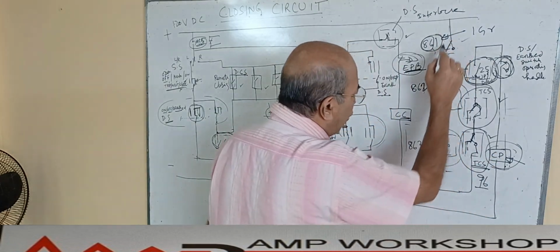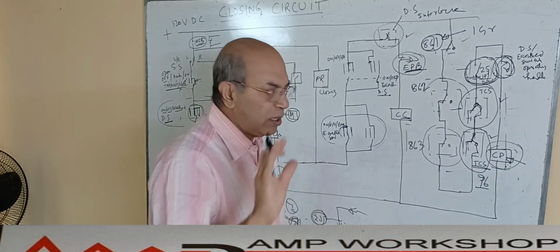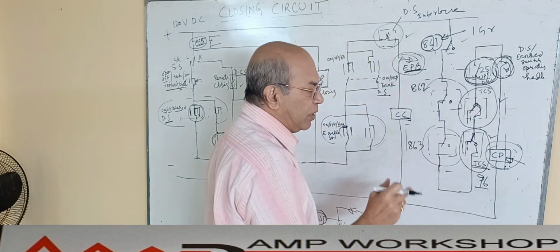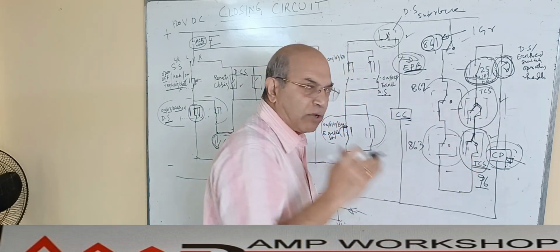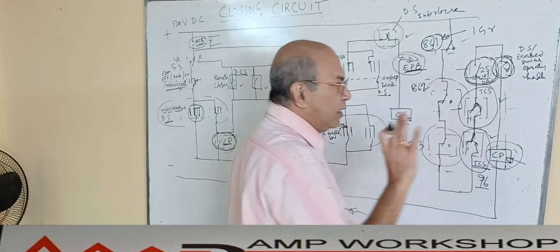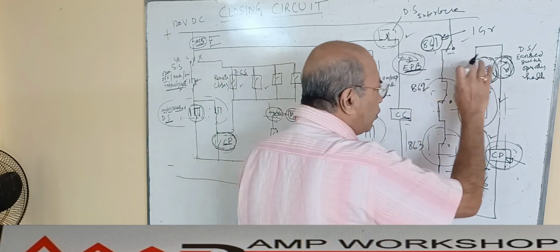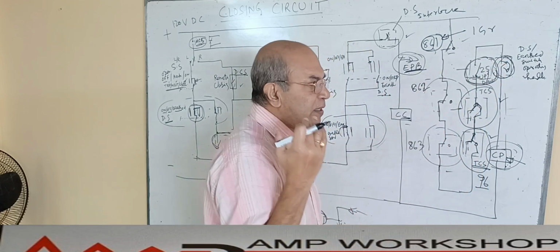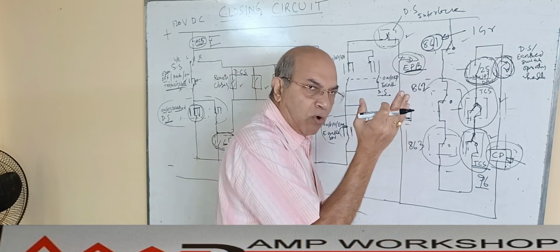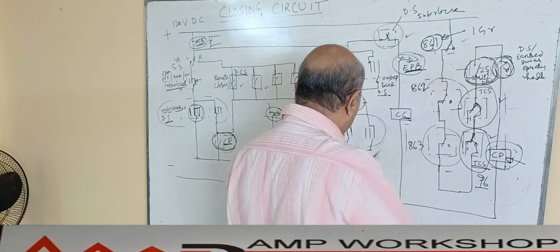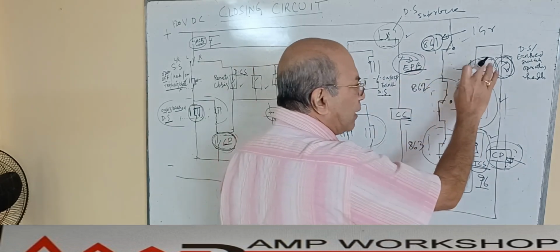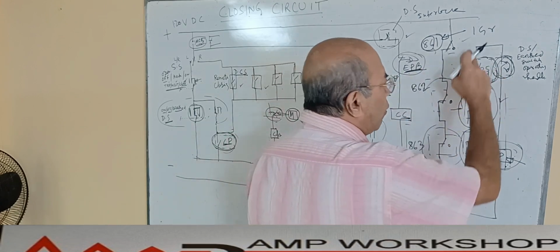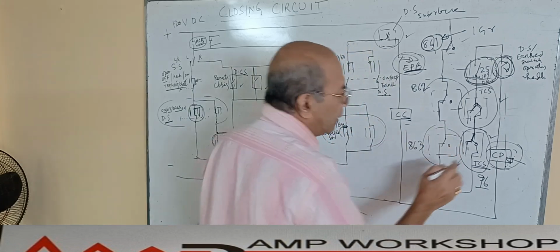Then the lockout relay not operating means there is no fault in the circuit. Both trip coils or a single trip coil, whatever the combination, both the trip coil and its associated circuit are in healthy condition and ready to trip. Downstream interlock means the downstream disconnector is not earthed, it is in the ON position. And if there is a synchronizing provision, the synchronizing relay is giving the permissive, and the local earth switch I am not going to operate. When all these conditions are met, then there is a CP.